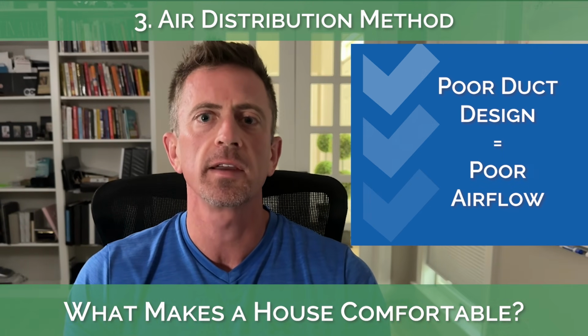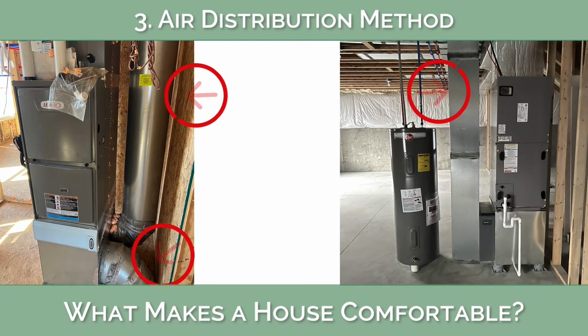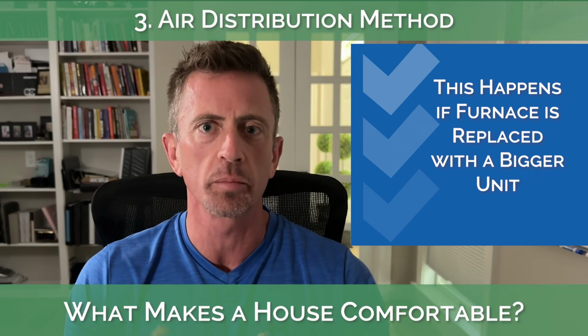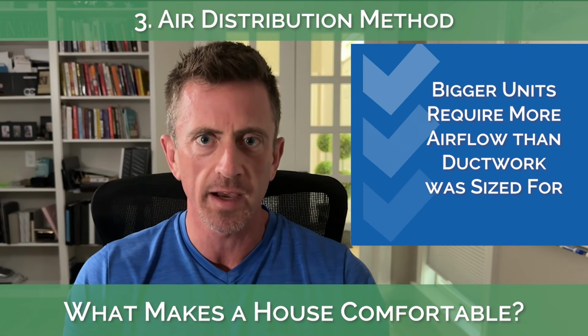A poorly designed duct system will not move enough air to and from the rooms as it should. We often find the return air side of the duct system is usually the problem, and specifically, the return drop and trunk line are too small for the amount of airflow needed by the heating and cooling system. A lot of times this happens because the original furnace or heat pump was replaced by a bigger unit at some point, which requires more airflow than the original ductwork was sized for.